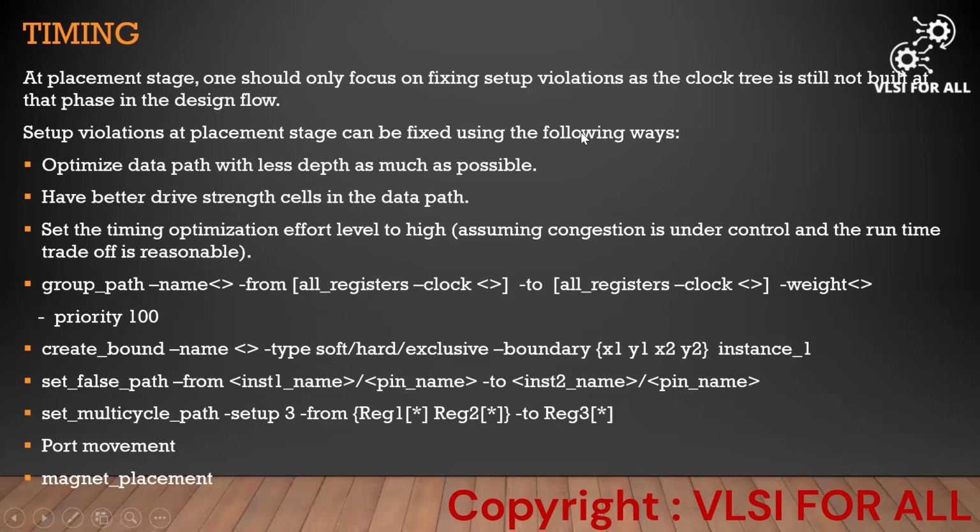While fixing the setup, a timing path has the data path and the clock path. If the data path depth is very large, meaning the logic depth is more, we can provide some extra cycle to capture data properly. For those cases, we'll give the set multi-cycle path command, hyphen setup 3, hyphen from register to register,